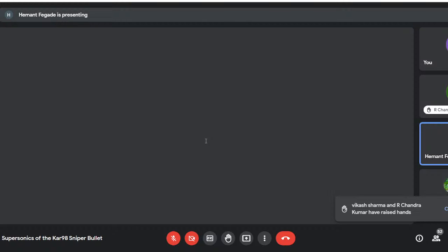You also need to make sure of the turbulent intensity ratio that you're going to maintain. So it's usually 5 and 10. The turbulent intensity is kept as 5, and I think the dissipation is kept at 10, so you can probably reduce it to 1 and 10 or 1 and 7. So accordingly you can have that.